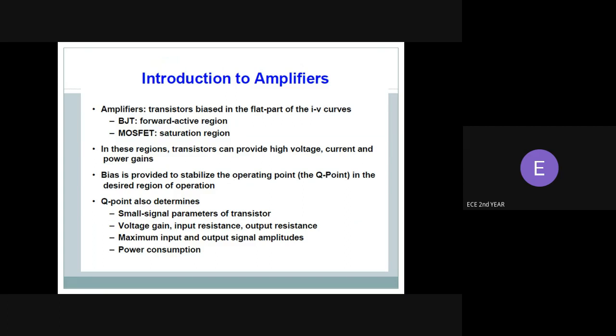In common collector or grounded collector configuration, the collector is connected to the ground or the supply. This collector terminal is common to both the input and output. The input signal is connected directly to the base terminal, while the output signal is taken across the emitter load resistance as shown. This type of configuration is known as a voltage follower or emitter follower circuit.